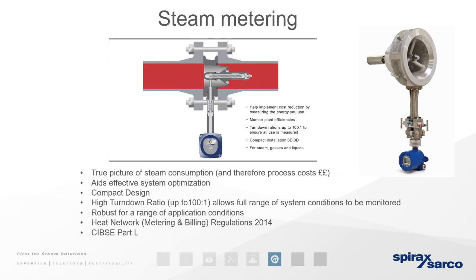The nice thing about the steam flow meter is that it records everything every minute. If you have a trend line on it, it can show you what happens. As soon as you start utilizing more steam within a section, it can show you either the inefficiency of that system or a problem where you might have a failed open steam trap that is now requiring much more steam than what the process usually requires. And therefore, it is also a matter of finding fault within that system.